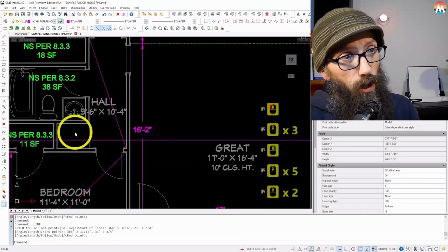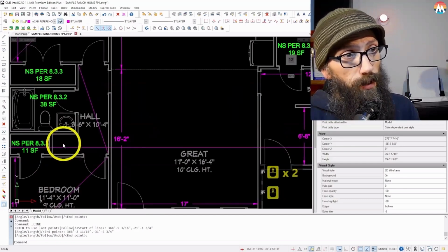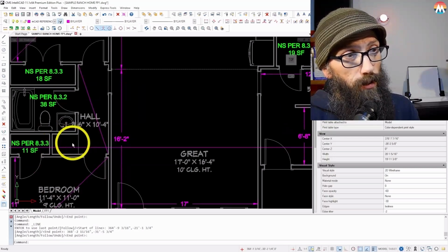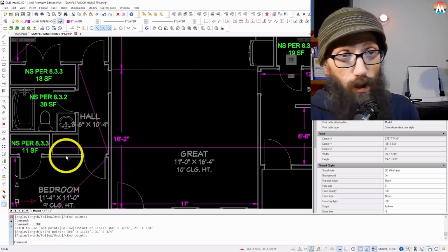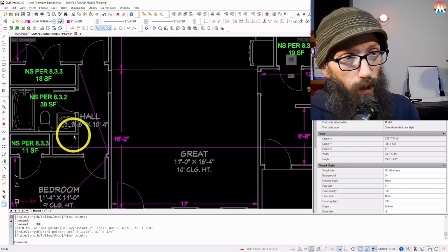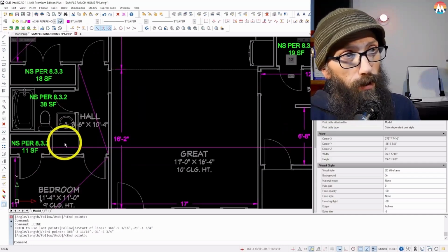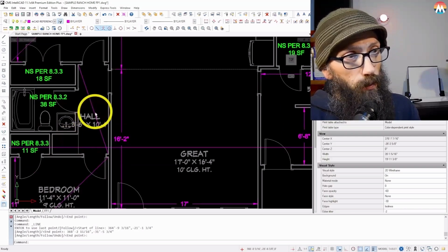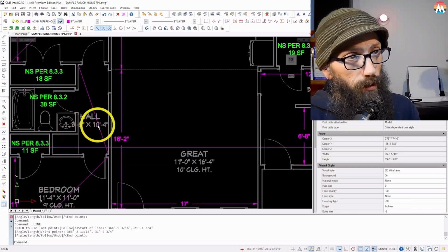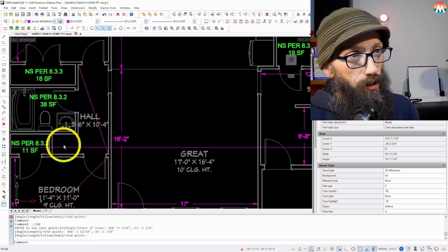Something to note, this hallway, this is just like a linen shelf or a linen closet in here on a shelf. If we were to put the sprinkler over here, you would end up with what's called a shadow area by NFPA, and up to a 5 square foot shadow area is legal, but we will place our sprinkler so that it sprays into that.